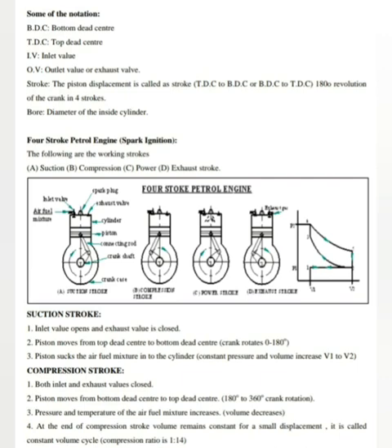Suction stroke. At the beginning of the suction stroke, the piston is at the top dead center, or TDC, and is about to move towards the BDC, meaning bottom dead center. At this instant, the inlet valve is open and the exhaust valve is closed.